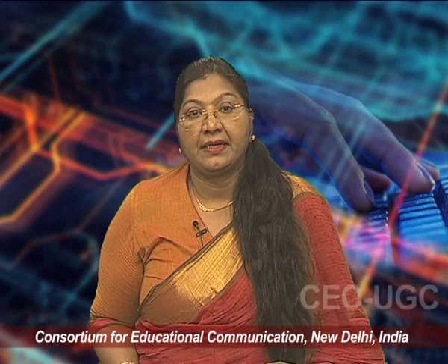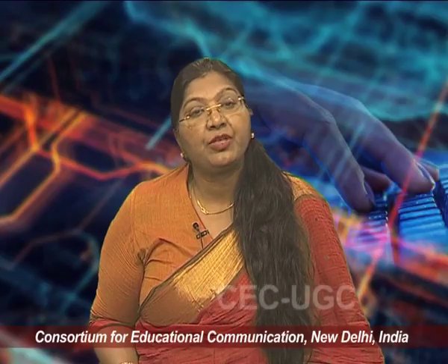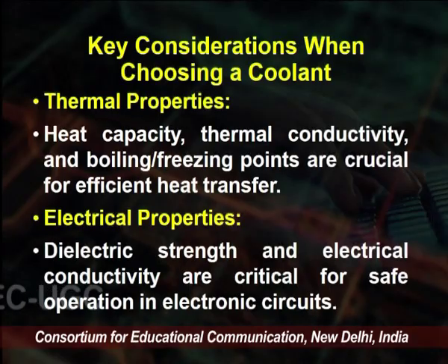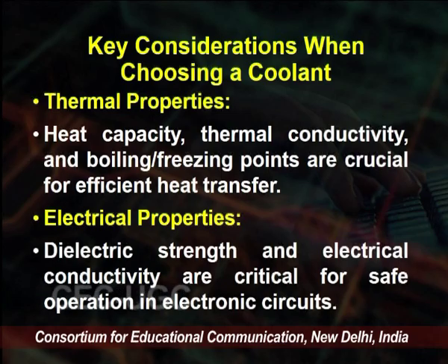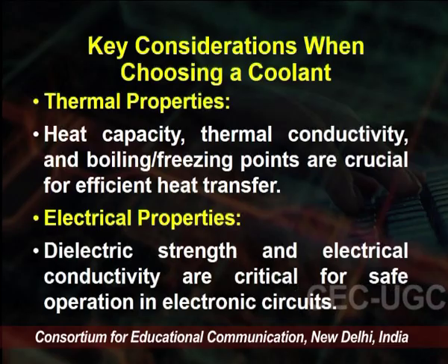So if we consider some key points for choosing a coolant, there are some properties which we have to keep in mind. First is the thermal properties. Here we have to note the heat capacity, thermal conductivity and the boiling and freezing points, which are crucial for efficient heat transfer. Another is the electronic properties, in which we have dielectric strength and electrical conductivity, which are critical for the safe operation of the electronic circuits.